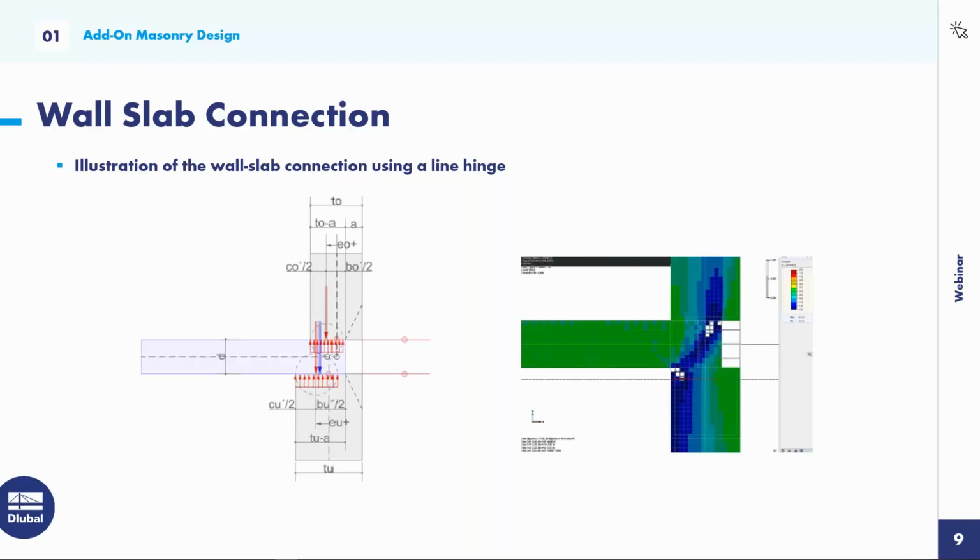As you all know, the slab, the concrete slab for example, does not lie completely on the masonry wall. There is mostly an offset, and that's the reason why the material model itself cannot react completely right at this point. In principle, the corresponding moments are already entered into the system through the concrete slab. For example, with a bigger slab span, there is a bigger moment in the wall. If the moment cannot be transferred by the wall, then the material model responds.